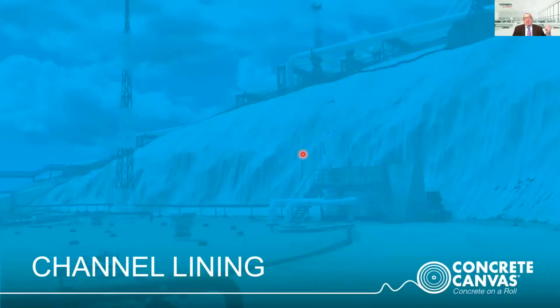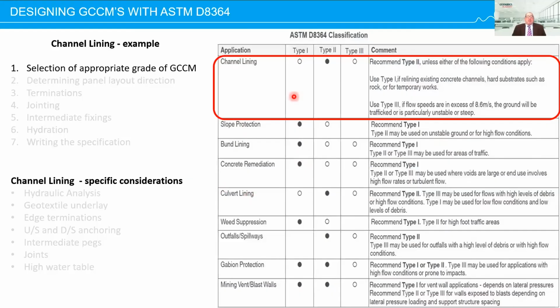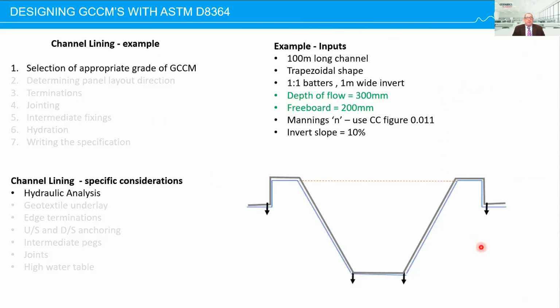Channel lining application. So channel lining, as far as selection of the appropriate grade, we go back to our adapted table here. We use a type 2 GCCM unless there's other factors. Here's a cross section that I put together for a job that we looked at. It was a 100 meter long channel, trapezoidal shape, 1-to-1 batters, 1 meter wide invert.